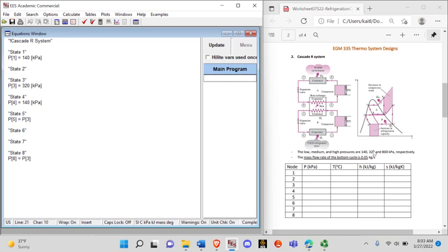Okay. And the high pressure is 800 kilopascals, and that's of the condenser. You can also see here from the TS diagram, constant pressure. Oh, I'm sorry, before we go to the high pressure, constant pressure also is at state 2 for the medium of 320 kilopascals. So for state 2, P2 equals P3.